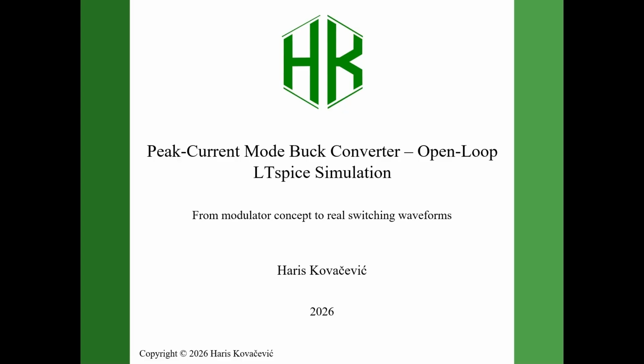The goal here is not controller tuning and not closed loop design. The goal is to understand what actually happens at the switching level, how the inductor current ramp interacts with the comparator, how PWM is generated cycle by cycle, and what the key waveforms really look like in practice.